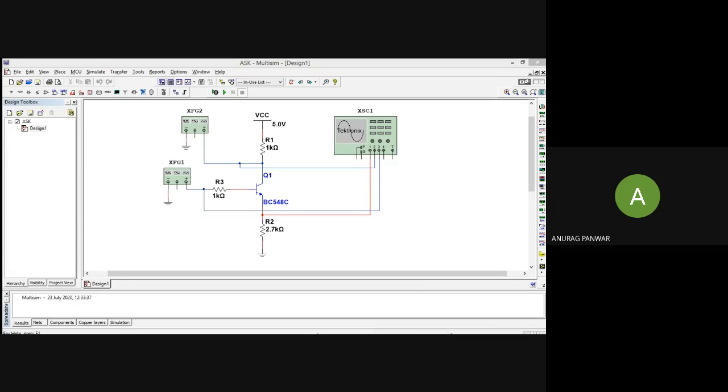I just opened the values of the function generator. In it I have given a digital signal. Okay, that is function generator 1. At function generator 2, I applied a 500 kilohertz sinusoidal waveform. That input is going to the collector region. This is your carrier frequency. So when the transistor is on, the carrier frequency will go from collector to emitter. But when your transistor is off, none of the carrier frequency will go through the transistor from collector to emitter.